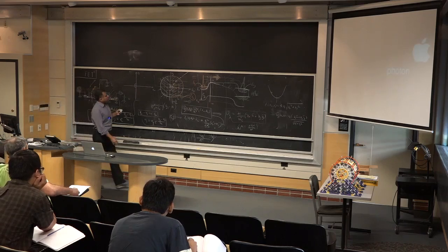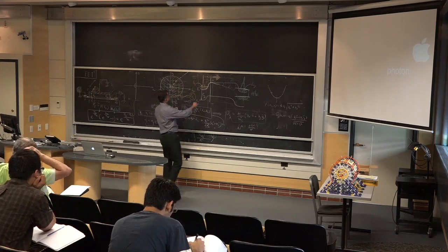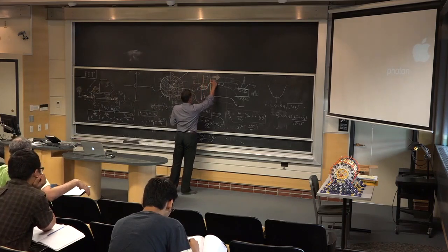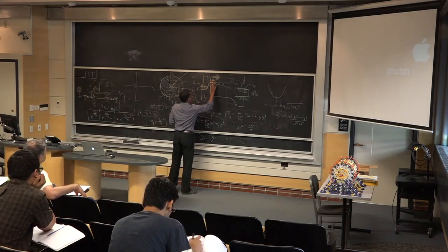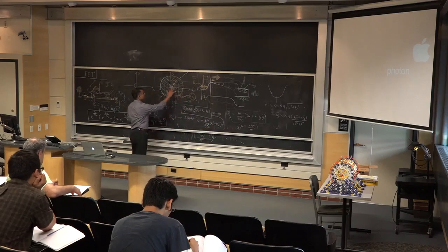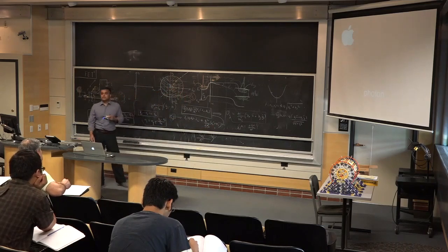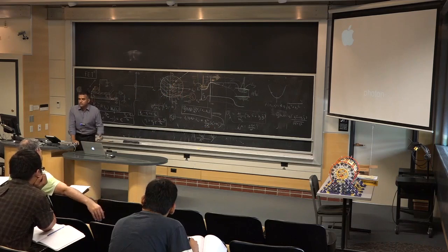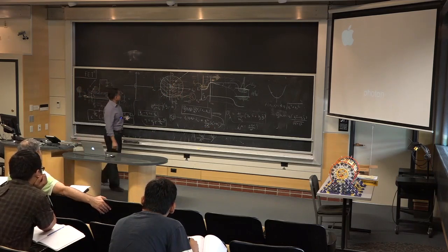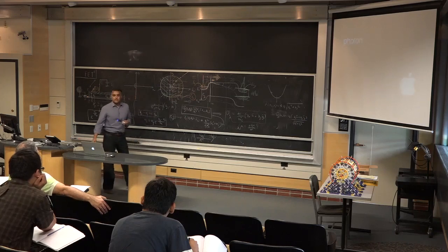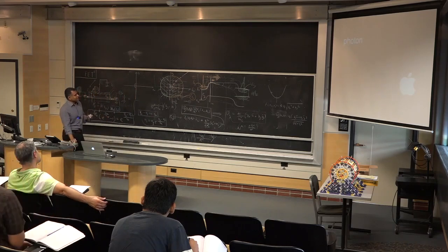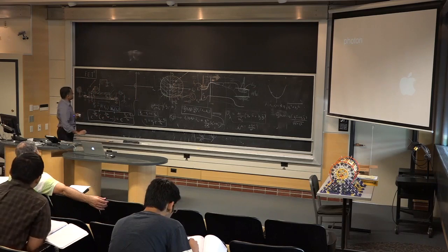But now, what's going on with the carriers injected from the source? This is the tricky part, which one might first say remains exactly the same. That's the first thought, because the barrier height has not changed. So it's exactly the same. But the correct answer is it's going to increase. It's going to increase, and that is the heart of the FET. That's the most important thing about the FET.